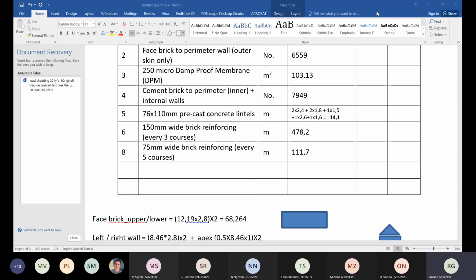Right, so basically I want you to calculate those 2 for me, because remember, it's not just a simple calculation. You have to subtract for all your openings, depending on how many courses of brickwork you have in the opening. You also have to include your brick force in your gable, and that can get a little bit tricky. So I want you to do the calculation, and that will be for your next tutorial. I'll post on Moodle the calculations that I've done, and I'll take away the ones that I want you to do for now, and then you can work through those.